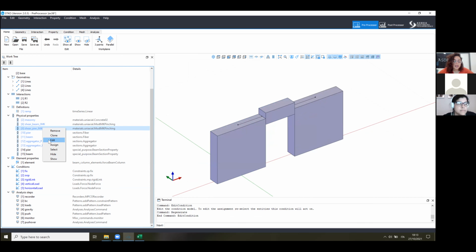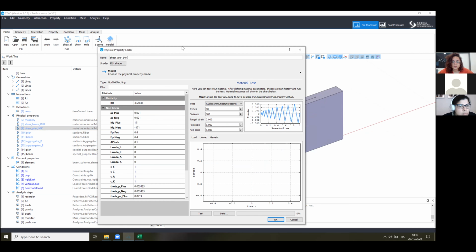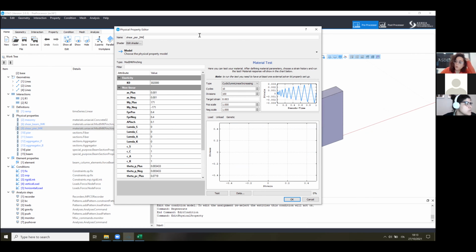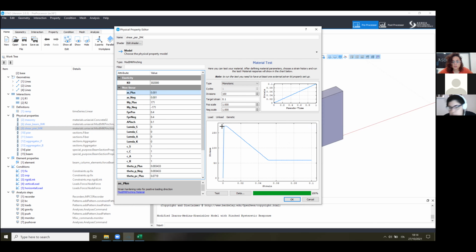So what we can do is add shear characteristics with one of these materials. This is just an option. You can use either Pinching4, a hysteretic material, or whatever you want to mimic your shear behavior. I'm just going to show you my monotonic response. This is the shear that I want to mimic for the masonry. I didn't use any hardening ratio for this plateau, just a very, very small one, otherwise I had instabilities in my structure.